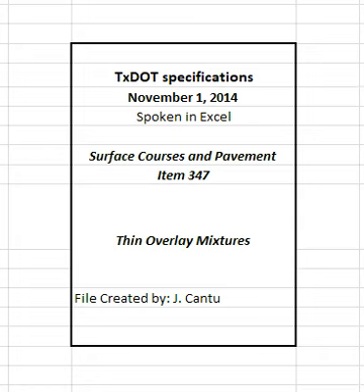4.7.2 Tack coat. Clean the surface before placing the tack coat. The engineer will set the rate between 0.04 and 0.10 gal of residual asphalt per square yard of surface area. Apply a uniform tack coat at the specified rate unless otherwise directed. Apply a uniform tack coat to all contact surfaces of curbs, structures, and all joints. Allow adequate time for emulsion to break completely before placing any material.